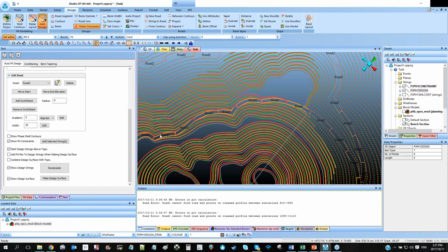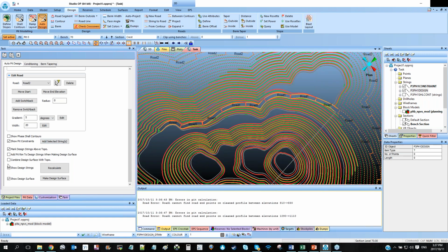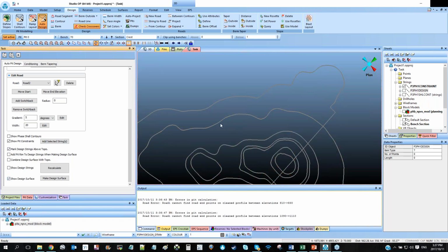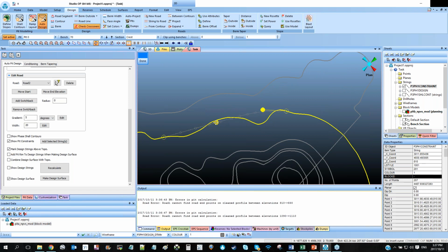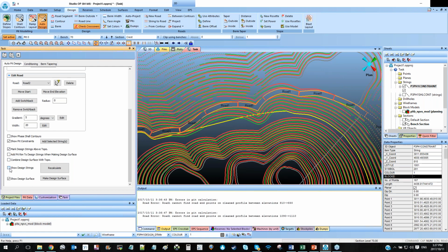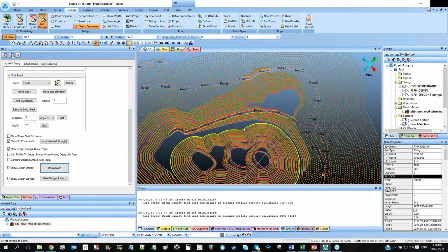Shapes like this make my road too windy, and I don't like that. So I could do some editing in here to make my life a little bit better for those roads, for those truck drivers. So what I would do, I'll just perhaps use ICS, and say from there to there, just do some smoothing there, create a little bit of a better path. Done. I just see the recalculation of that. It's taking longer because it's streaming with the topo. Yeah, there you go. It's a much better road. Looks much better as well.